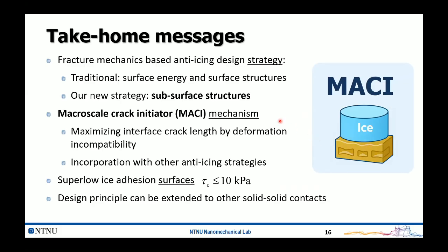Based on that, we propose this macro-scale crack initiator mechanism, which maximizes the interface crack length by increasing the deformation incompatibility or the stiffness mismatch. And it can be easily incorporated with any other strategies. Then, based on our strategy and mechanism, we have prepared different types of super low adhesion surfaces with adhesion below 10 kilopascal. At the end, this design strategy can be easily extended from the anti-icing application to other types of solid contact problems.